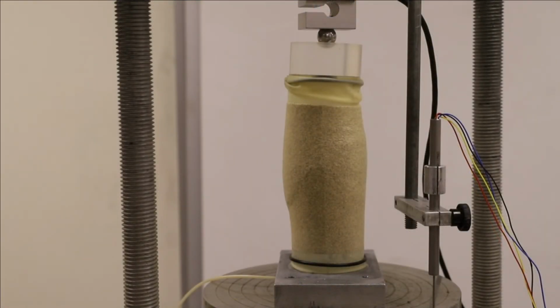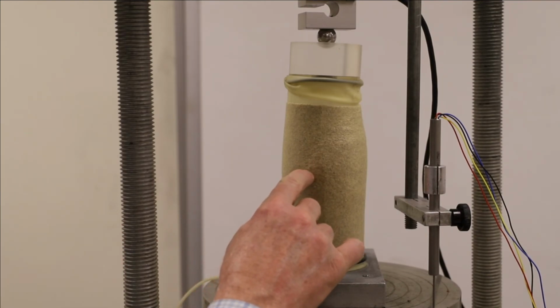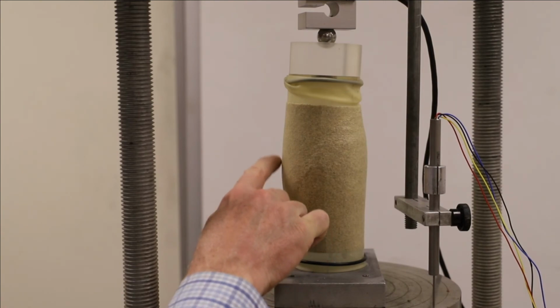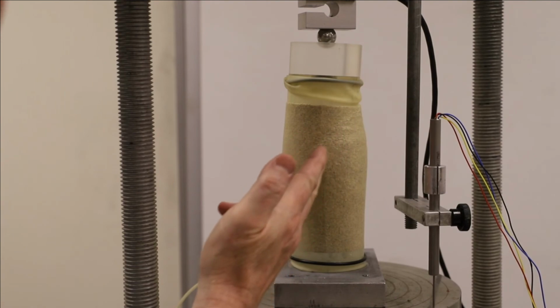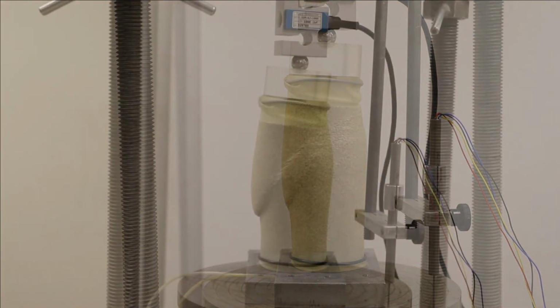Okay, so we've exceeded the peak load. The load has actually been dropping now for a little bit, and we can start to see why. We have a different mode of deformation happening, and usually this happens in a direction that we can't see very well from where the audience or the camera is looking, but this one's beautiful. You can see a ridge here developing in the surface of the soil, right? There's a bulge and then a sharp ridge at an angle that goes up there, right? So we have a distinct